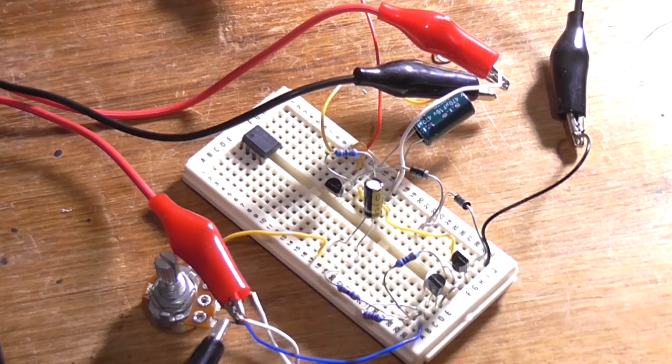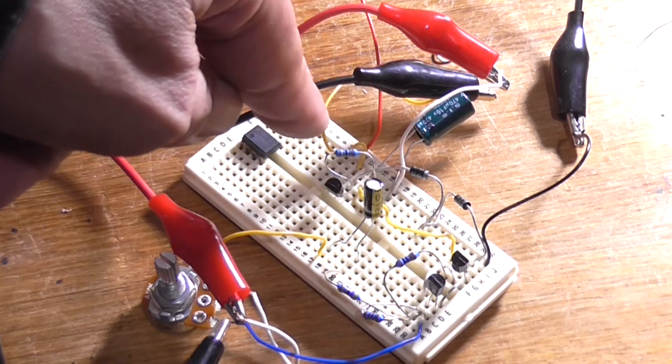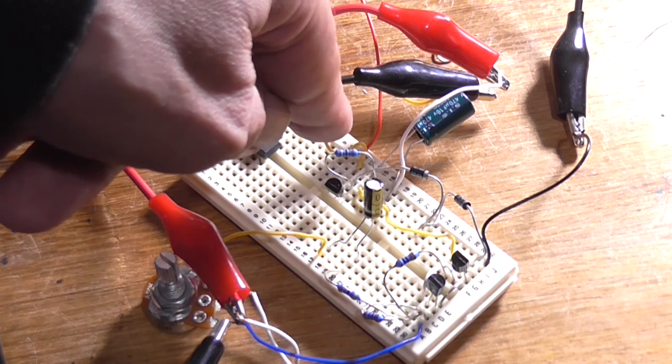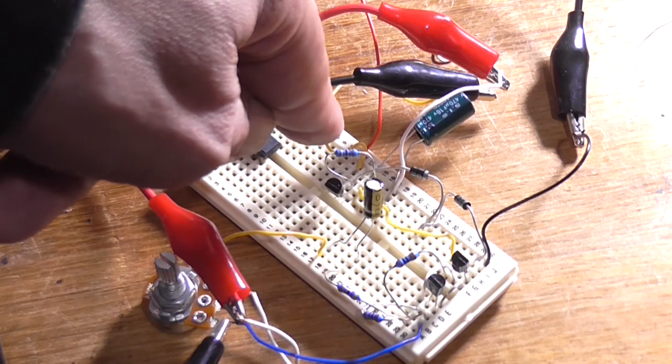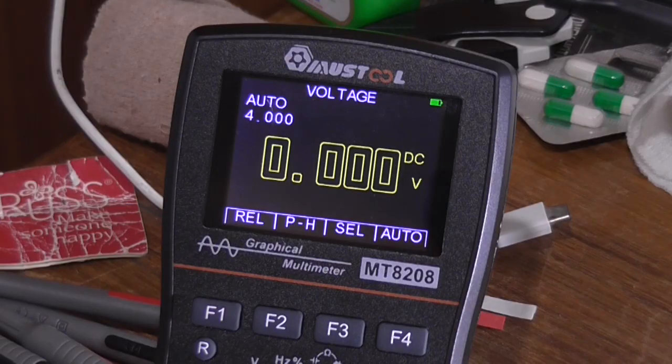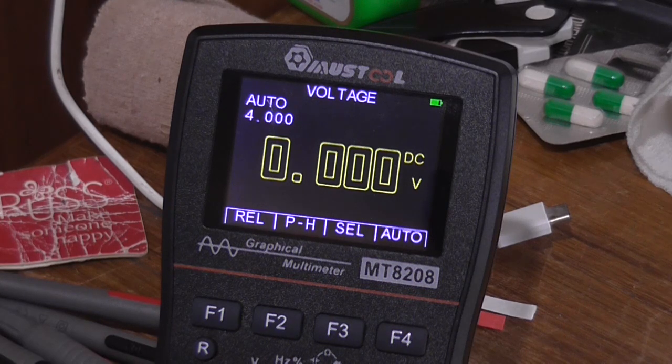I don't know if it sounds any good yet, but what I want to do is measure more than calculate what the voltage drop across this resistor is. It's actually a 2K2, I didn't have a 1K5. I've got a 1K3 I could probably stick in there. Alright, I got my meter carefully hooked up across that resistor and not shorting anything currently, so I'll just do this as a quick test.